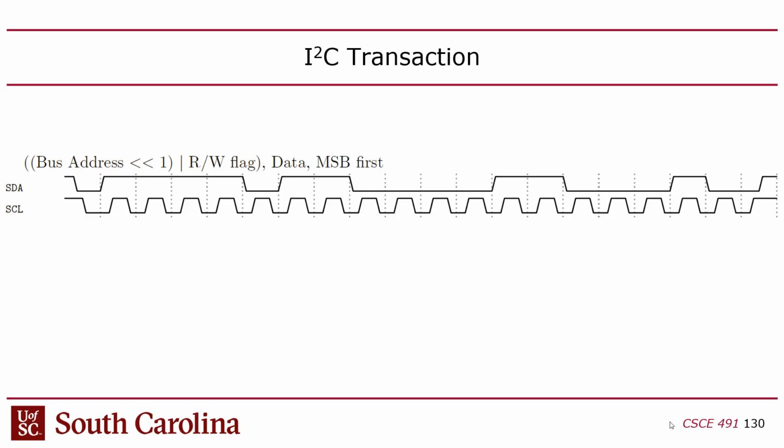What if the data was already high? Well, the data could have already been high, but if it wasn't, that would have been a bad acknowledgement, right? But yeah, clock high, data high, that's stop, right? So we have to get the clock up first because the whole point is that we want to change the data while the clock is high, which is the special condition.